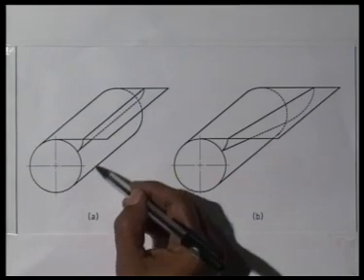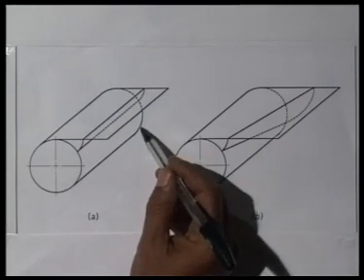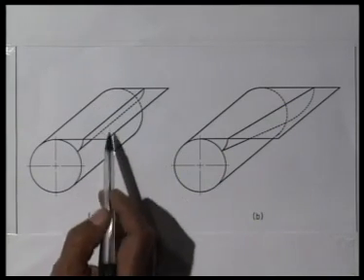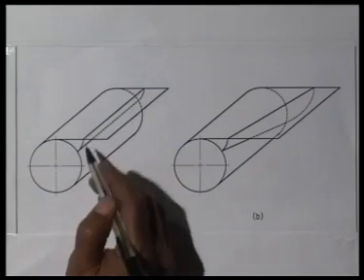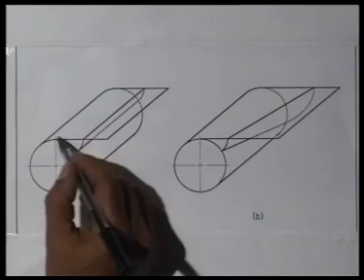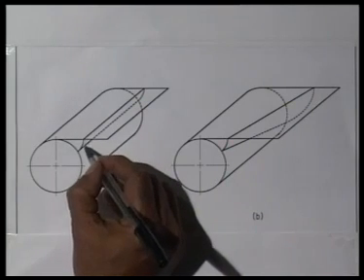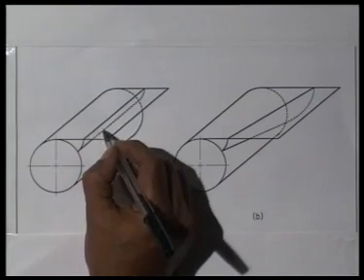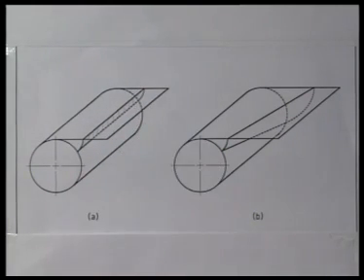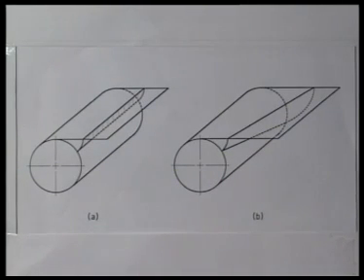Actually, this represents the base circle from which this string is unwinding to generate this involute profile. So if we consider the width of the gear, that is this base circle, I can think of a base cylinder. Then this strip of tape or paper which was wound on this base cylinder, if it is unwound, then the surface that is generated by any line of this paper, like this particular line which was here, is generating this involute surface, and the gear tooth of a straight tooth spur gear was this involute profile. Let us see what happens in case of a helical gear.